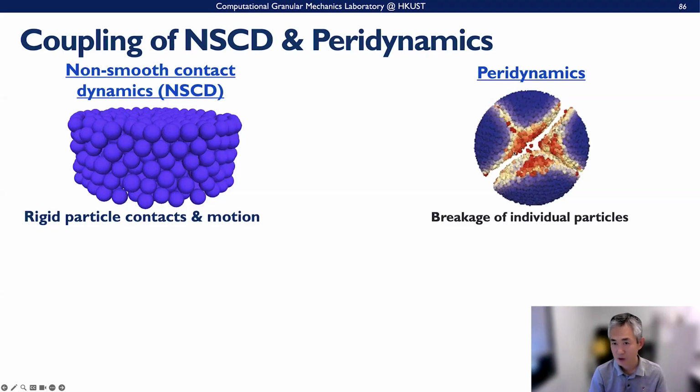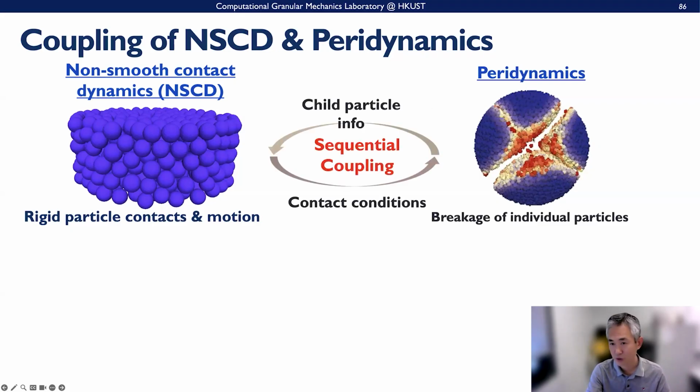and send it to this PD dynamics, but we retain the initial contact conditions if it's surrounded by 3 or 4 contacts. We apply the same contacts to these particles, and then we run this PD simulation at the same contact levels, forces, and positions, to verify whether or not it breaks. Once it breaks, we return this broken child particle and put it back in the position of the original particle, and let it establish an equilibrium position, and do this in a sequential way, right?